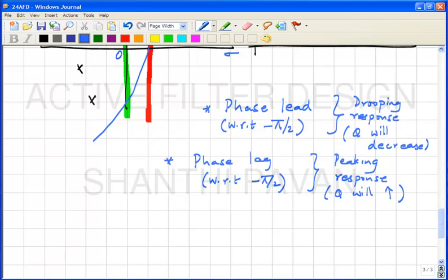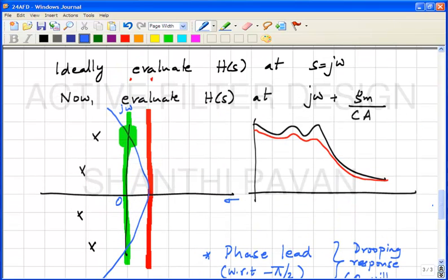Okay. So some people try to increase or mitigate the effect of parasitic pole by deliberately reducing the gain of the integrators. It's not a very robust thing because the DC gain depends on Gm and R naught, right? Whereas the excess phase will depend on something else. So it becomes very difficult to cancel this over time and temperature variations and all this stuff. Okay, but this is just something to be aware of.